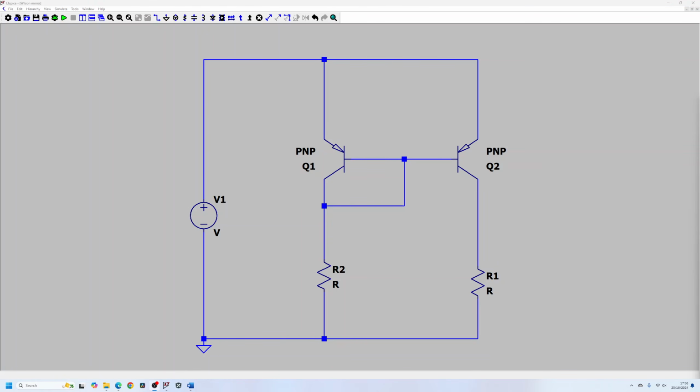So here's how the circuit works step by step. A reference current, Iref, basically going down this path, is established by connecting this resistor over here. And you know the voltage on this node over here due to the power supply. So obviously this would be a known power supply. Let's say it is 10 volts in this case. So you have 10 volts over here.